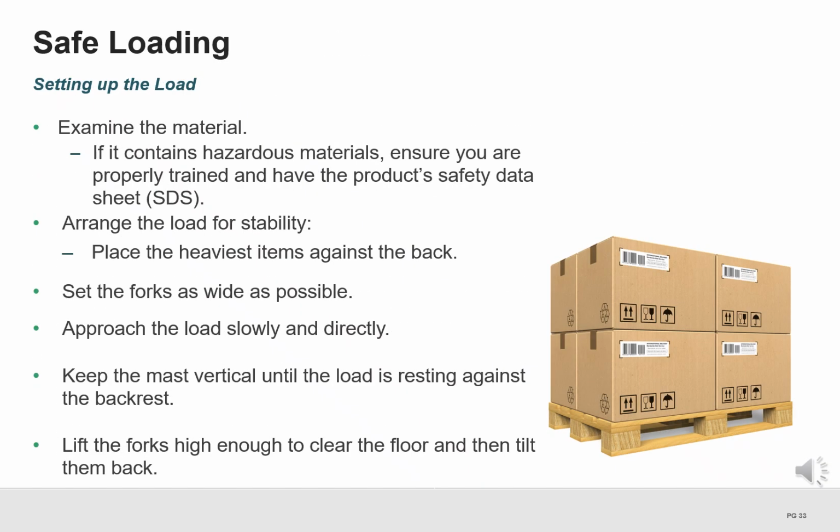Before lifting any load, take a moment to examine the material. If it contains hazardous materials, make sure you are properly trained and have access to the Safety Data Sheet, or SDS. Arrange the load for stability by placing the heaviest items closest to the backrest. Set the forks as wide as possible to support the load evenly.